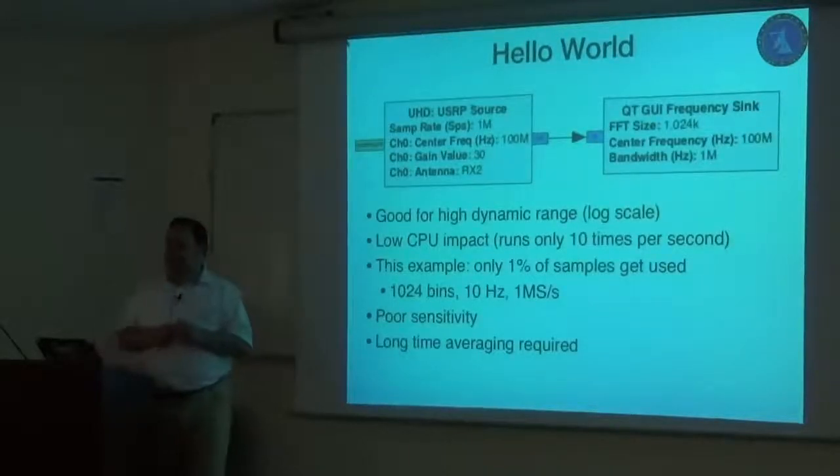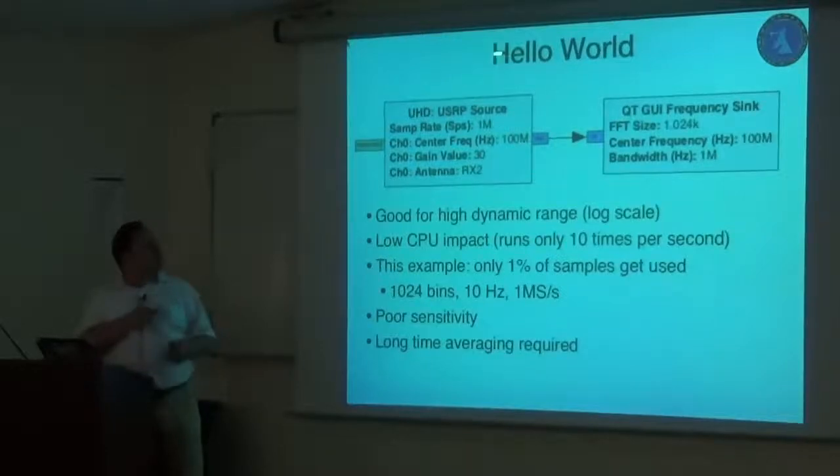So let's get back to the basics. And this is really, again, what JM asked earlier. This is the hello world, I would like to say, of playing with GNU Radio. You have whatever signal source you have, you put it on a frequency and a sample rate, you connect an antenna, and you dump all of that in the FFT block, and you see a pretty graph with the strong radio stations and the weak radio stations, and you are FFTing the signal.